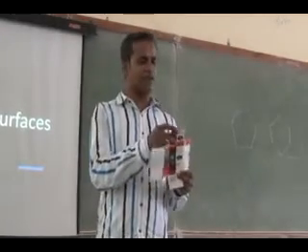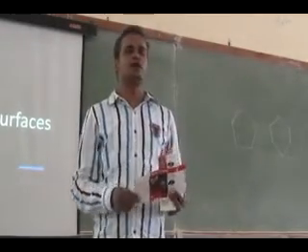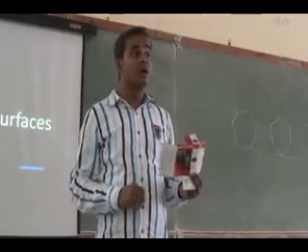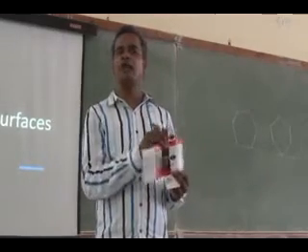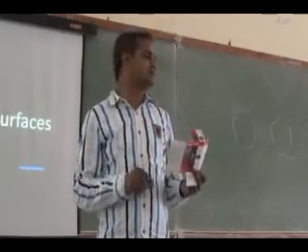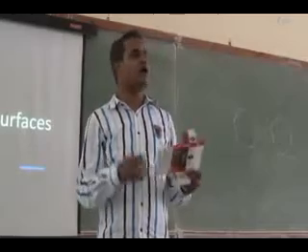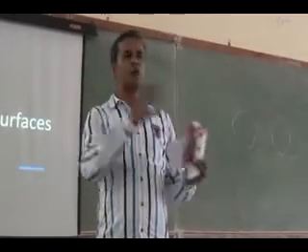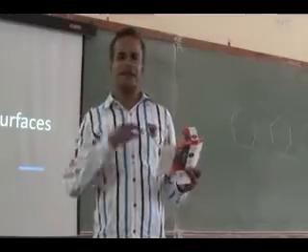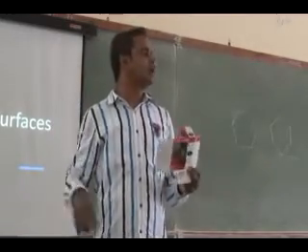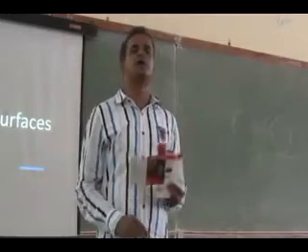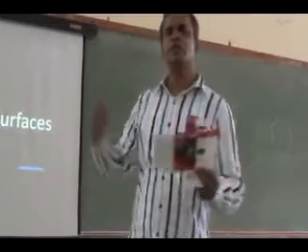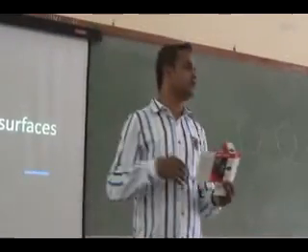If it is a sheet metal component, we can cut the exact shape. Suppose I have an automobile body, the car structure. If I know the development exactly, I can draw that sheet alone and use it for my product. Otherwise, an excess amount of material will be used and wasted.